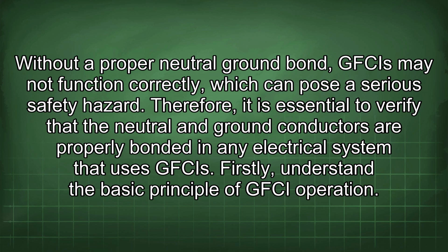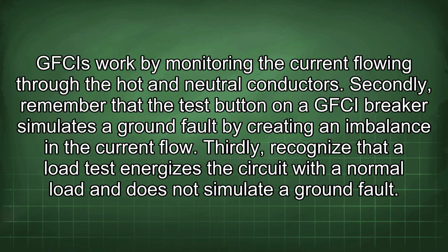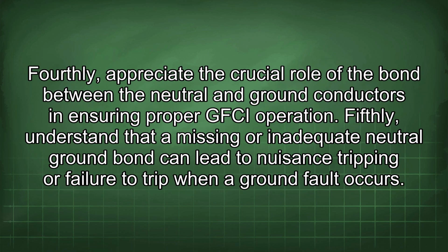Firstly, understand the basic principle of GFCI operation. GFCIs work by monitoring the current flowing through the hot and neutral conductors. Secondly, remember that the test button on a GFCI breaker simulates a ground fault by creating an imbalance in the current flow. Thirdly, recognize that a load test energizes the circuit with a normal load and does not simulate a ground fault. Fourthly, appreciate the crucial role of the bond between the neutral and ground conductors in ensuring proper GFCI operation. Fifthly, understand that a missing or inadequate neutral ground bond can lead to nuisance tripping or failure to trip when a ground fault occurs.